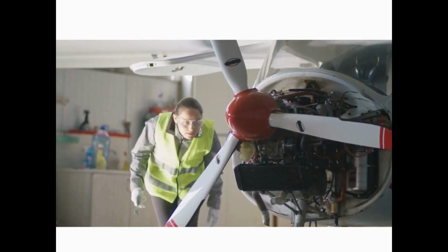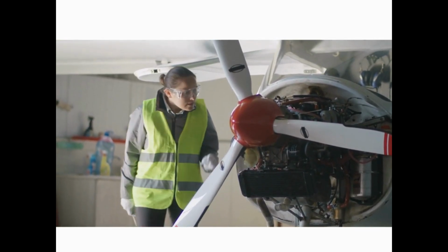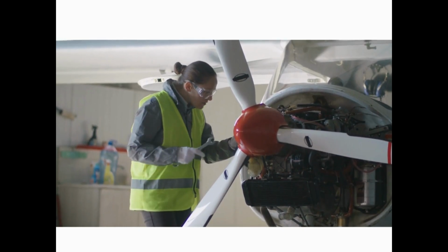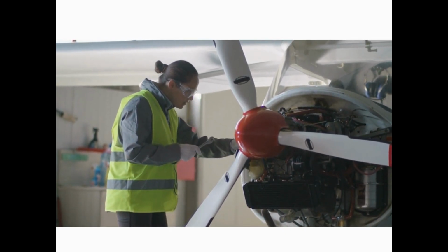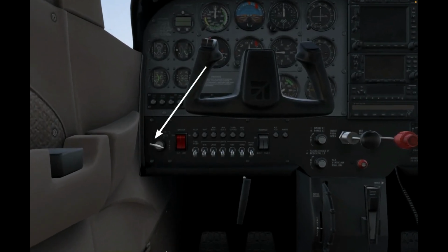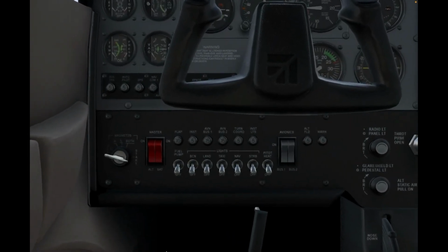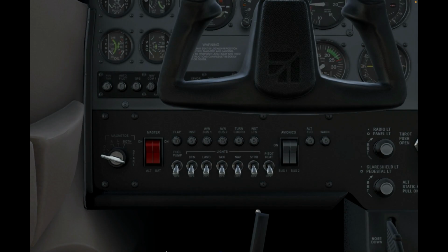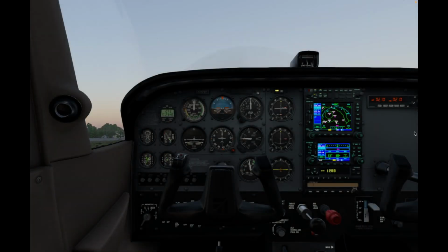There are some other issues that you can experience with your aircraft engine. Some examples include loose or broken wires in the ignition that can cause problems. For example, if the ignition switch is off, the magneto may continue to fire if the ignition switch ground wire is disconnected. If this occurs, the only way to stop the engine is to move the mixture lever to the idle cutoff position, then have the system checked by a qualified aviation maintenance technician.